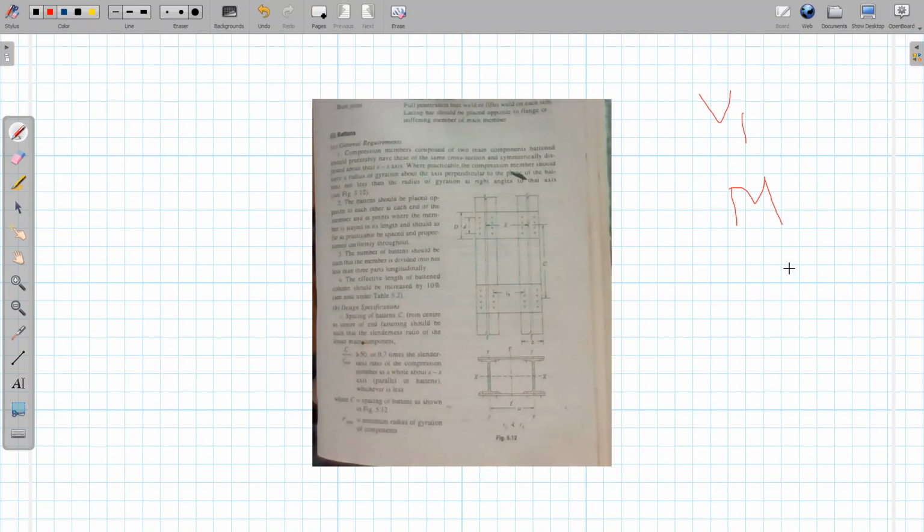Okay, calculate that value that we know. If you remember, we know it as FM. So once you know the FA value and then the FM value, then you calculate the net force. Okay, so the net force acting on the rivet must be less than the rivet value. That is what we did if you recall the eccentric connection. So the same steps are to be followed here when this is a riveted connection.